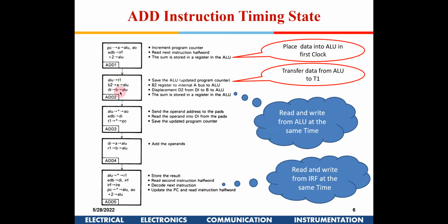So here, if you see, something is being returned into the ALU, which is tasked with a new addition, whereas the result from the previous operation is being pushed into T1 also, right? So now you will find there is an issue out here. We will see how this issue is resolved by using a multiple phase clock. For the time being we'll leave that issue like that, and we'll revisit it.